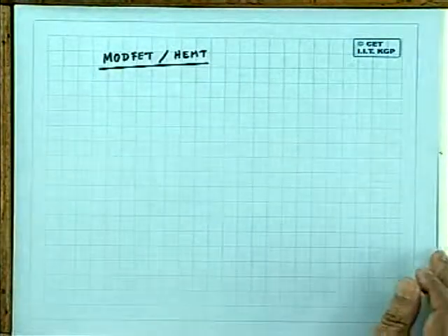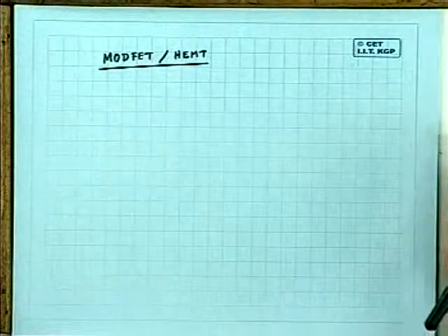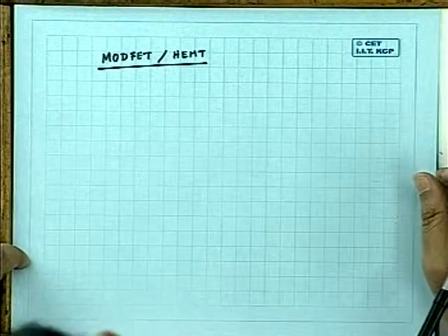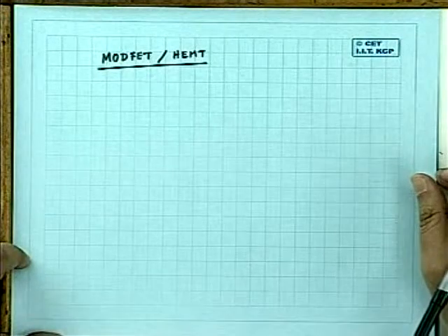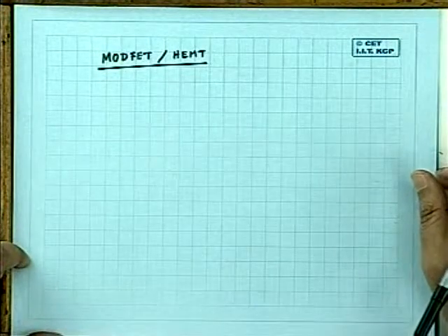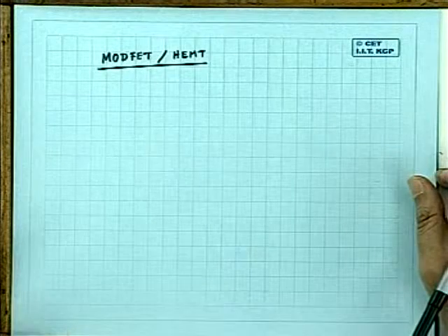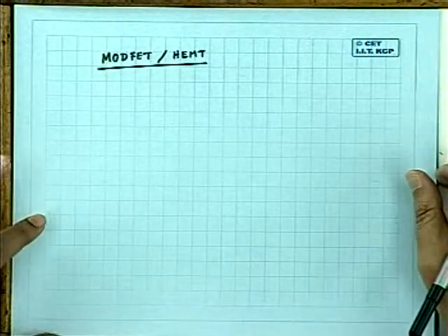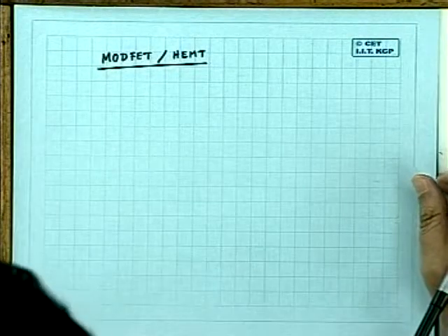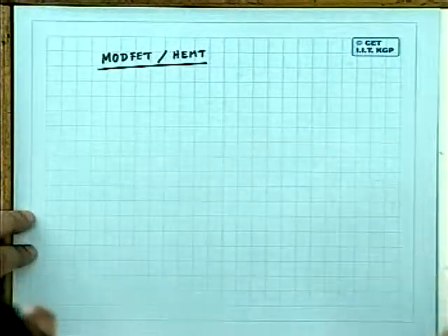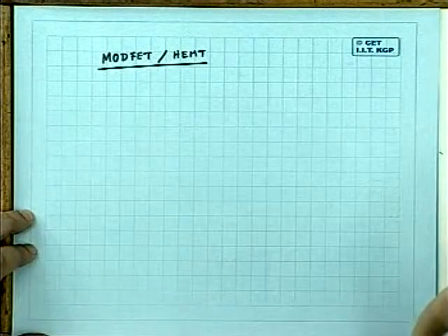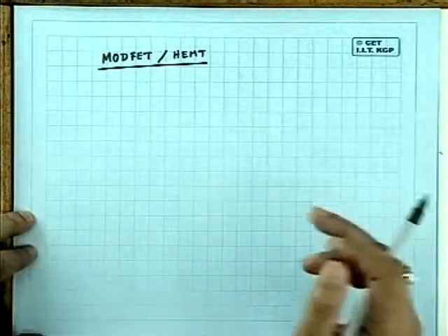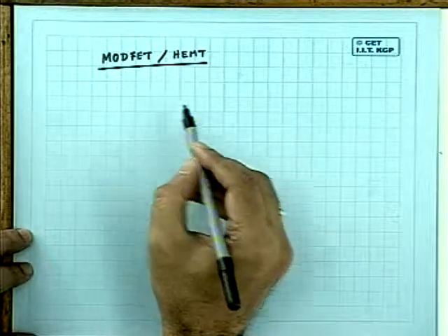It can be gallium arsenide based or indium phosphide substrate based. Today, gallium nitride is a very interesting material coming up. Silicon carbide is also a very interesting material coming up, but traditionally the substrate was gallium arsenide, and there was some interest in indium phosphide in the recent past. Till today, these are the two important substrate materials. However, there is tremendous potential for gallium nitride particularly. It looks like this.